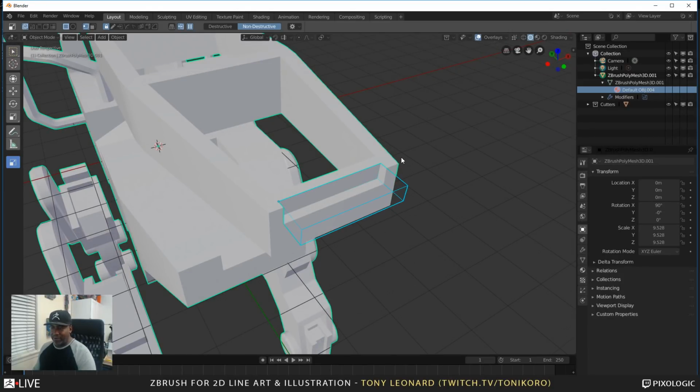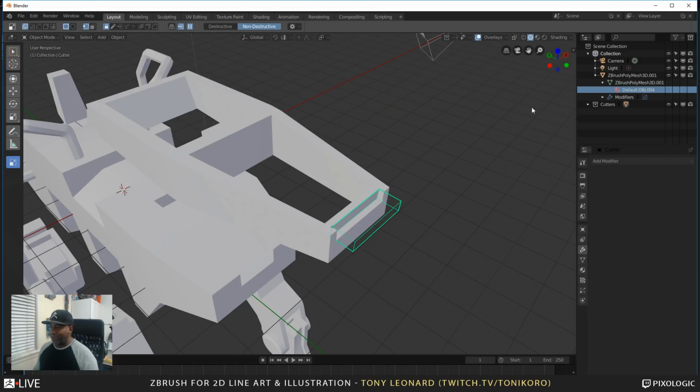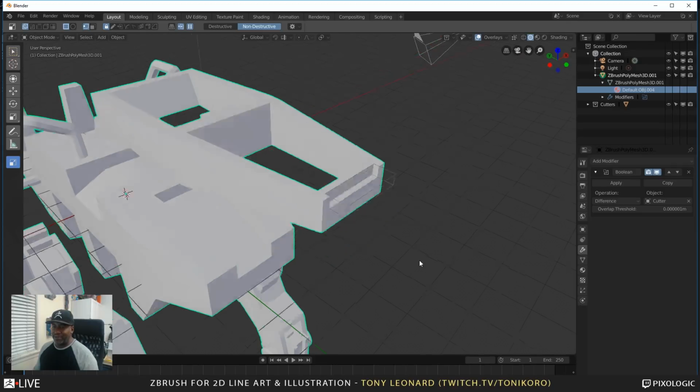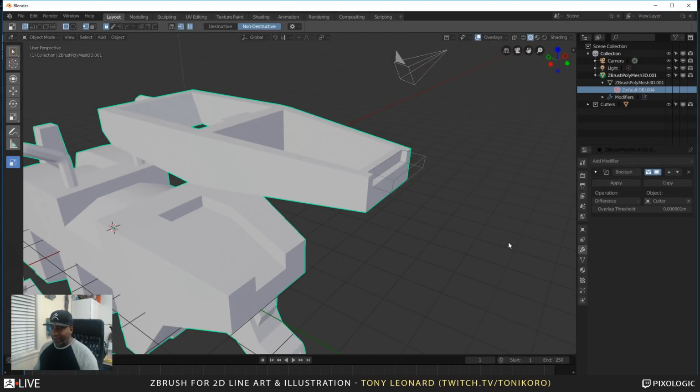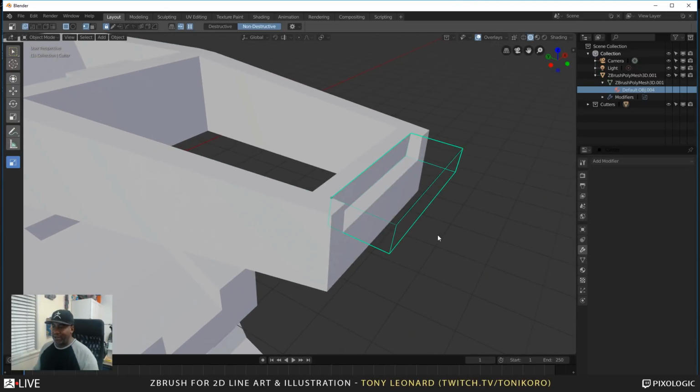If I actually unhide all of the objects, this is what's happening: there's a shape that I've just drawn out, and it's gone along the normal of the object and drawn a box. With that box, it'll actually add a modifier to itself so that I can go and just cut it, right? So this actual Boolean modifier is what's happening to the surface of this, right? With that in mind, I can still edit this box as long as it's live.